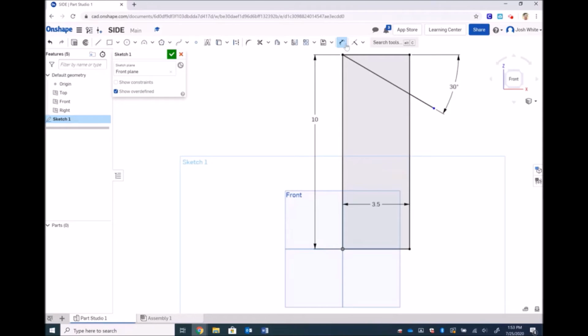I need to do a point at this location in order to show that dimension. So from there to there, it's approximately 8 inches, which is what I did on the drawing, and it's not necessary to do that dimension. That's an over-constrained drawing. So we'll just undo that. So we have our angle set.